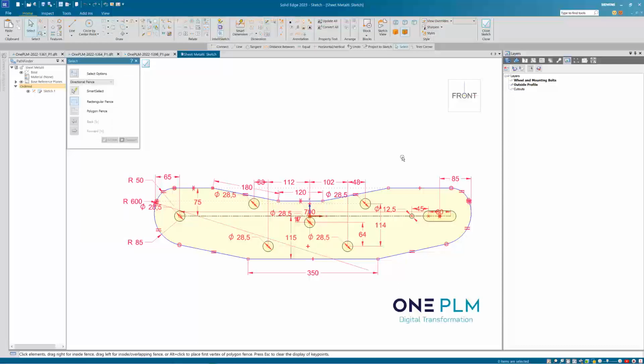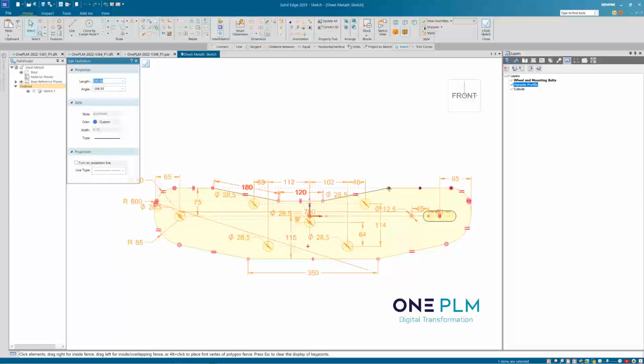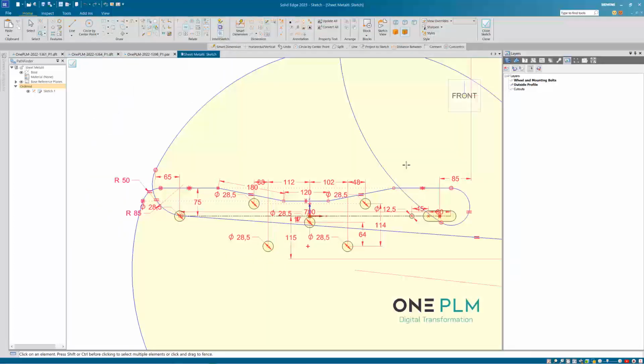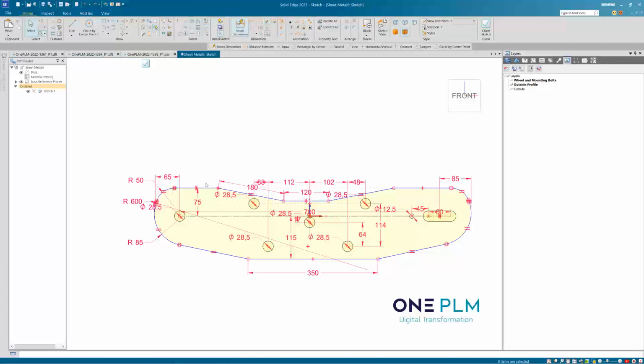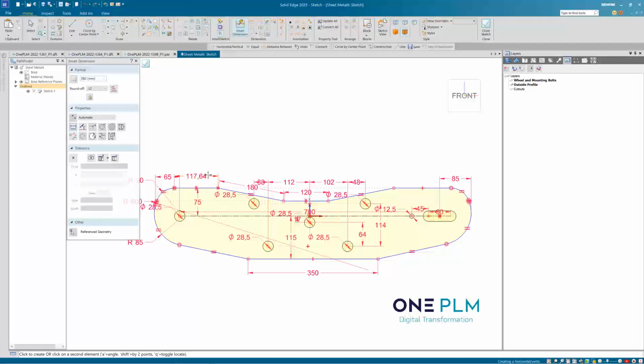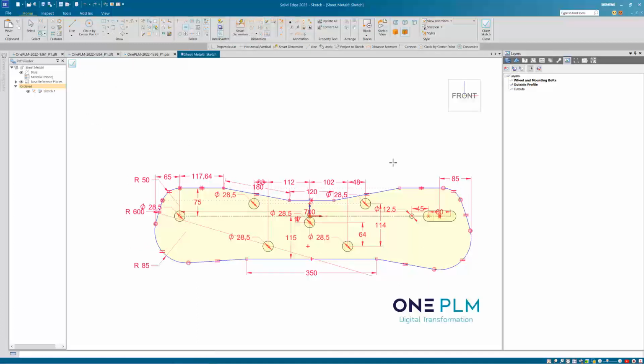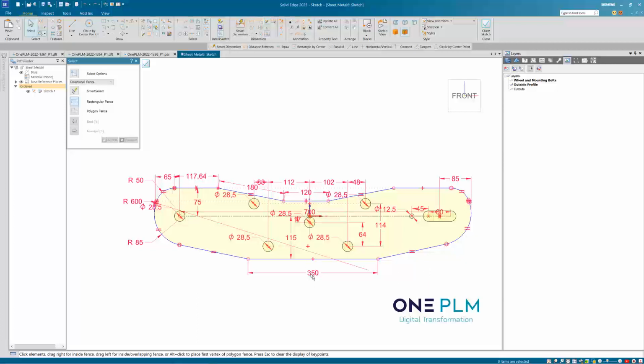We're trying to have it a little bit more predictable as we're working. If we click on a line and then drag an endpoint, we can see the degrees of freedom that we've got. So I can see that is moving left to right. If I do an equal between those two, that's going to cause a bit of a problem. So let's see if we can get an equal once we've got a dimension on there. That's not ideal.